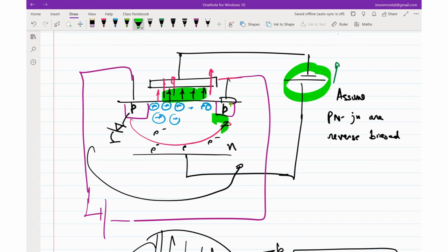So what's going to happen in just the semiconductor which is close to the surface? Arguably you will be seeing more and more electrons rushing away from that surface, and you'll be uncovering more and more immobile charges, right? So the amount of immobile charge that was there earlier, just around the surface, now if you go slightly beneath the surface also, you are going to see immobile charges. That's going to happen, but something more interesting happens.